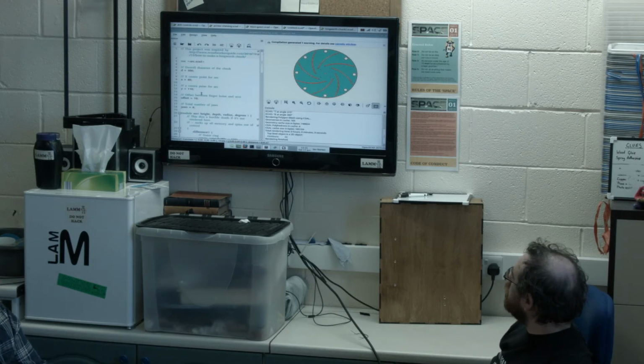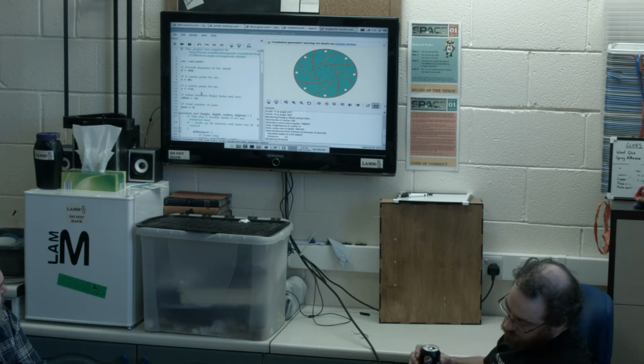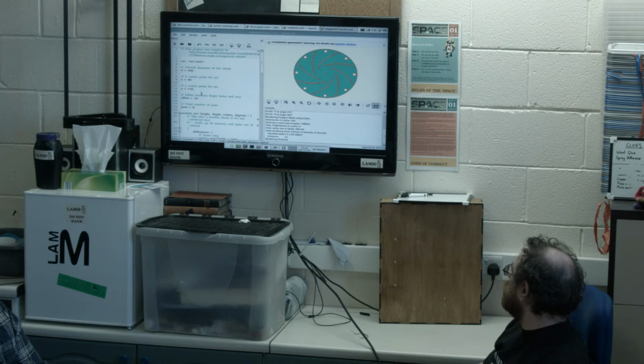But in FreeCAD you have a spreadsheet, like Andy told me, and you can import a spreadsheet from Excel or something like that, or create a new spreadsheet and put all your values there. Then you say this number cell has a name, and it's registered in the global variable thing, and then you can use that in FreeCAD.